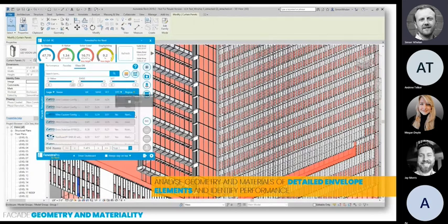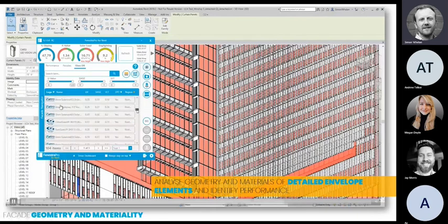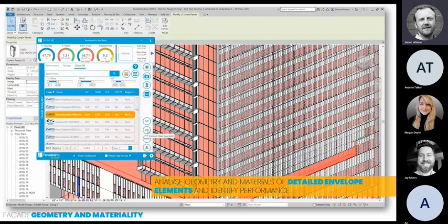So when you do select something, my dashboard updates and I can see all of the different components within that facade or that surface, and I can change them, right? So I can affect change on my materiality. Touched on this earlier on. We can search through a pretty sizable product database based on performance. So based on a U value that I'm trying to achieve or a solar heat gain coefficient that I'm looking for. Lots of other tools there I can use as well.